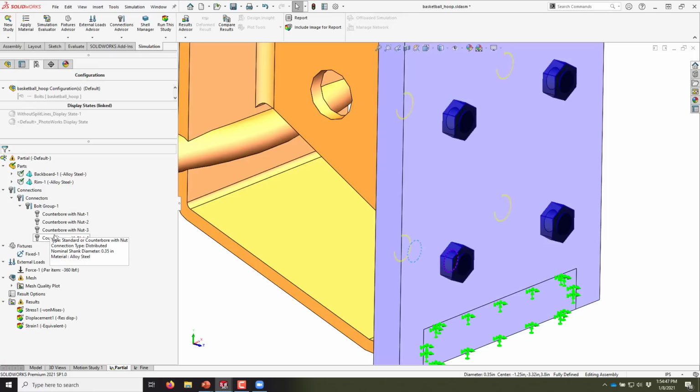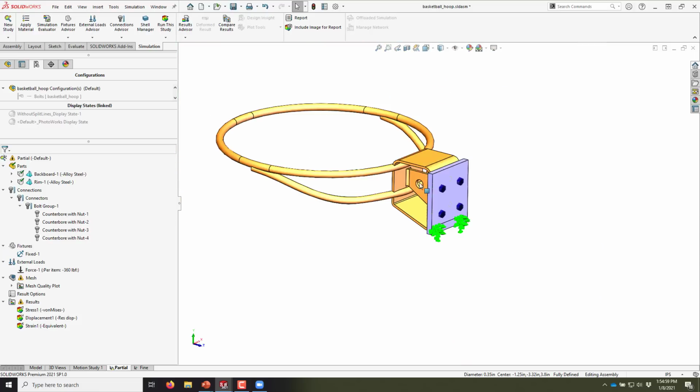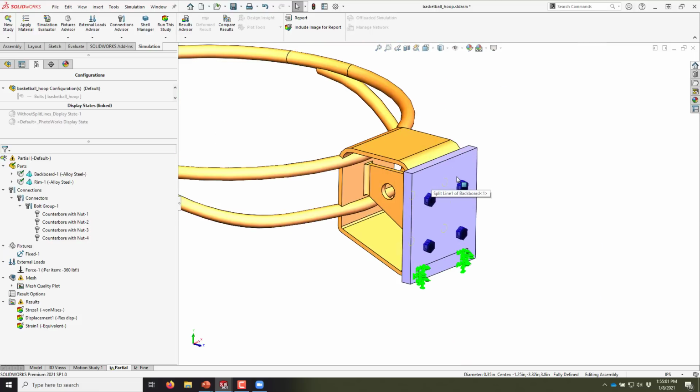A couple other ways you can do it. If you do a whole series, it'll automatically pattern the bolt to all the other holes without me having to do it. So if you created 100 holes as a whole series, this would automatically pattern all those holes for me. I wouldn't have had to create them all individually like this. But it does have to be a whole series.